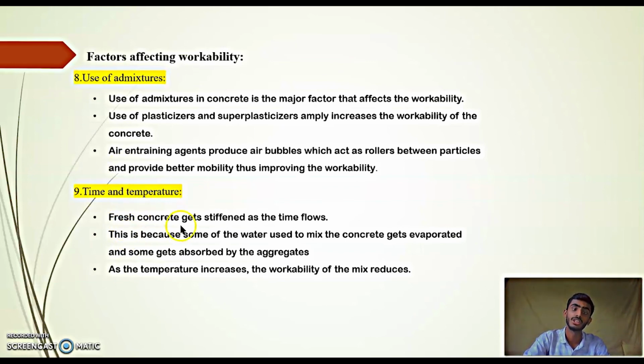This is because some of the water used to mix the concrete gets evaporated and some gets absorbed by the aggregates. As the temperature increases, the workability of the mix reduces. As I told, time and temperature are dependent factors for the concrete. Therefore, as the time increases, the workability decreases, and as the temperature increases, the water content reduces, and the workability also reduces. These are the factors which affect the workability of concrete.